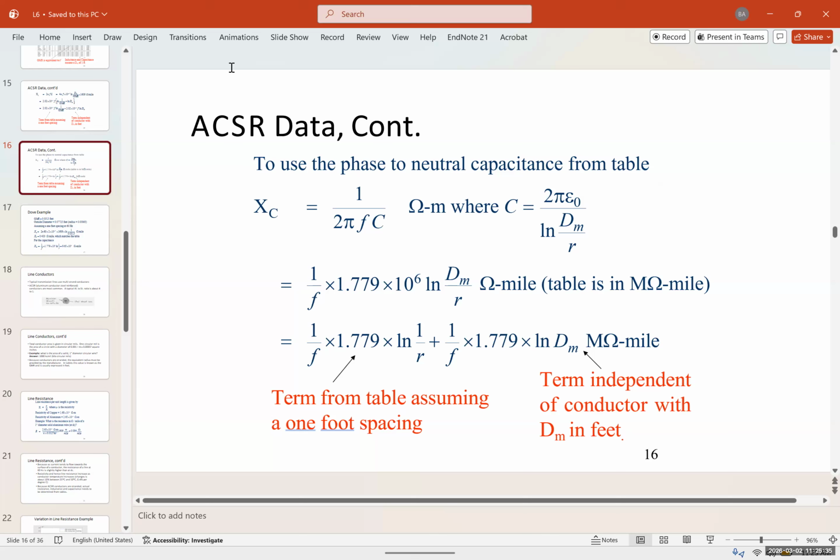We can just replace them, using just this equation, with the numbers that we have for GMR and for inductance and capacitance per mile, and we can easily find it for a 10-mile, 100-mile line with 10 centimeters distance, 1 meter distance, and 10-meter distance. When you want to design a transmission line, you have these tables, you just replace them, and you can find how much inductance and capacitance you're going to have. Using those two factors, you can find the reactive power and design your power factor compensation system for it.